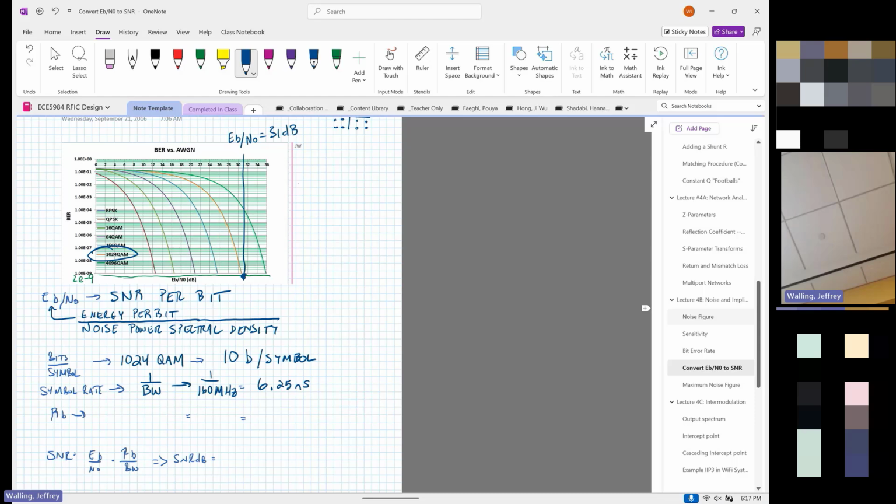Now, Wi-Fi 7 is 320 megahertz. So 320 megahertz, 4K QAM. So they've doubled the bandwidth, and they've increased the number of bits per symbol from 10 to 12. So they've done something like 2.4 times more information at their max rate.